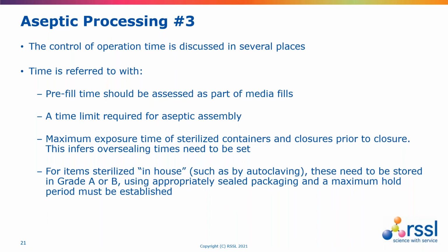That the time once a filling line or an isolator has been set up before filling starts itself should also be controlled. The exposure time for vials, particularly at point of fill, should be standardized, and also the hold time of any sterile equipment as well. So after equipment's been autoclaved and held in integrous wrapping, how long can that be held for? And again, including that into a media fill is a straightforward way to try and capture those elements.